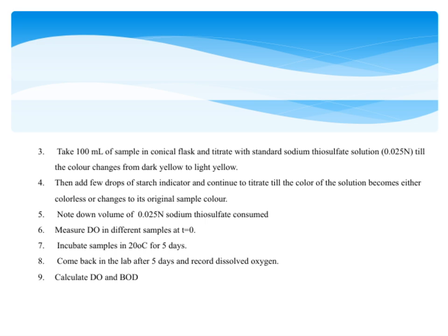Moving on, we measure the initial dissolved oxygen, or DO, in our samples at time 0. After that, we incubate the samples at 20 degrees Celsius for 5 days. This incubation simulates natural conditions and allows the bacteria to consume the organic matter, reducing oxygen levels over time. Finally, after 5 days, we come back to the lab and record the remaining dissolved oxygen.